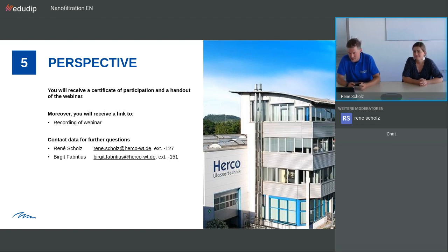Do you have an experience with ammonia removal by nanofiltration, pH of 7.15 to 7.4? Okay, there we would really need the complete water analysis, I think. In general, ammonia removal shouldn't be super high because it's monovalent too. But if you have these specific conditions with a pH, I think it would be really useful to have the complete water analysis to give you a qualified answer. So feel free to send us an email with the analysis and we'll respond and have a look at your project.